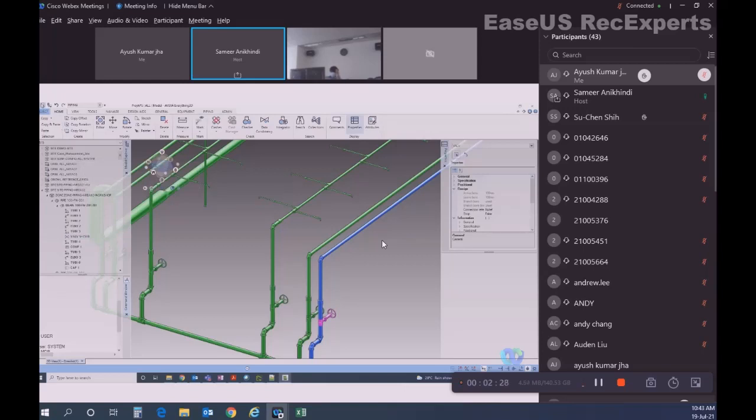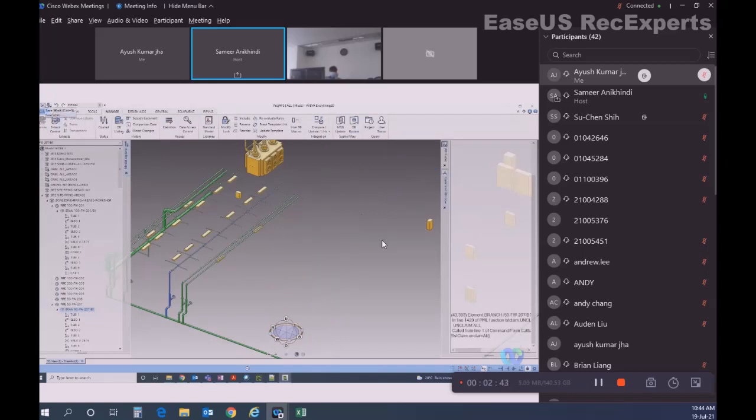I will save work, and you can see there's unclaim. While saving, you can unclaim also. There's a checkbox. If you check it, you don't have to go to the claim list menu. It will unclaim from here also. Save work. Let me go to the piping user, get work.